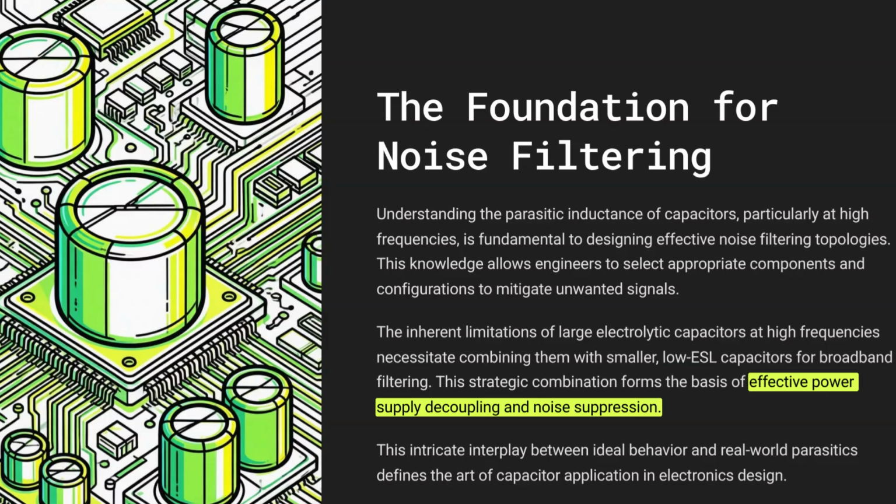Supercapacitors. We were talking about maybe 20,000 microfarads being big. Supercaps start at 1 farad. Yeah, and they go up to hundreds of farads. Their potential is massive, especially compared to batteries. A key thing is their longevity. They can be charged and discharged tens, even hundreds of thousands of times. A typical lithium-ion battery is dead after about 1,000 cycles.